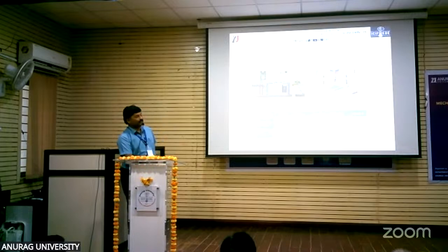This represents the experimental setup. Here I joined copper sheets of length 100 mm, width 50 mm, and thickness 1 mm. The welding machine is a 20 kilohertz ultrasonic metal welding machine with 3.6 kilowatt output power. The key parameters are pressure, weld time, and amplitude.